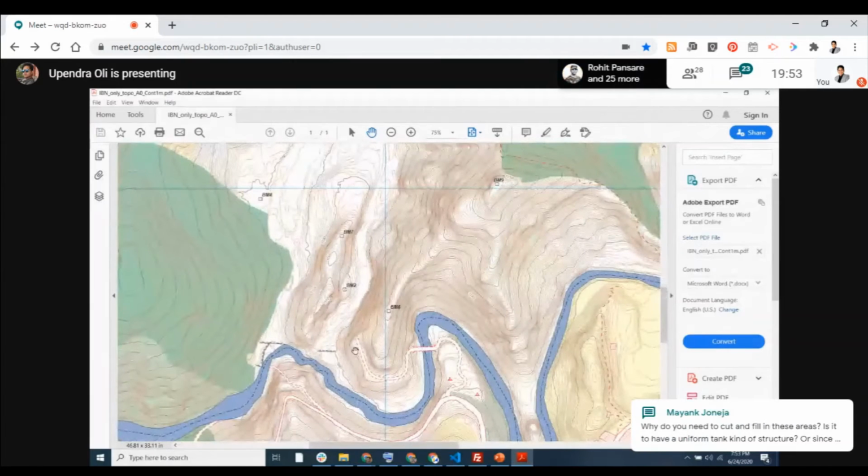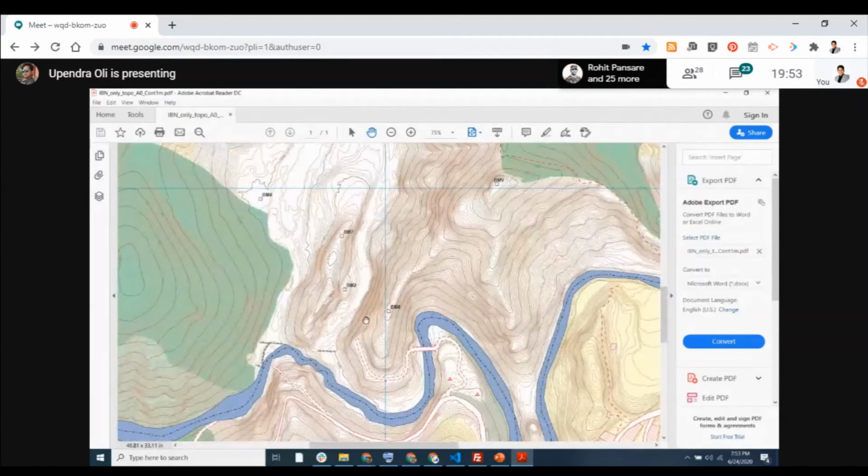because there is another advantage of doing drone survey, that is an orthophoto. By looking at the orthophoto and the video animations, you can easily get the idea of being there. So it will be very easy to plan things if we are familiar with this area rather than looking from a remote place.